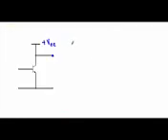The operation of a multivibrator circuit will be totally dependent upon the switching property of a bipolar junction transistor. When the bipolar junction transistor acts as a switch, it will have two states, on state and off state. A bipolar junction transistor is said to be in on state if I supply a positive voltage of plus VCC at the collector terminal when the input voltage Vi is greater than 0.7 volt. When Vi is less than 0.7 volt, this transistor will be in off state.